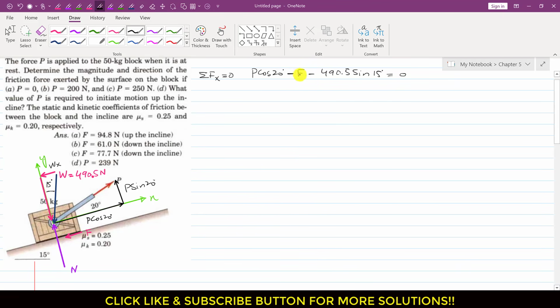We can write the friction force in terms of these two. If we bring this F to the other side, this will be equal to P cos of 20, and cos of 20 is 0.94, so I can write 0.94 P, minus 490.5 sine of 15, which is 126.95, so this is minus 126.95. Let's say that this is our equation 1.